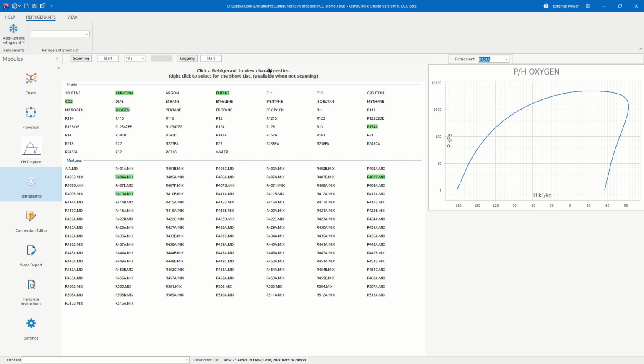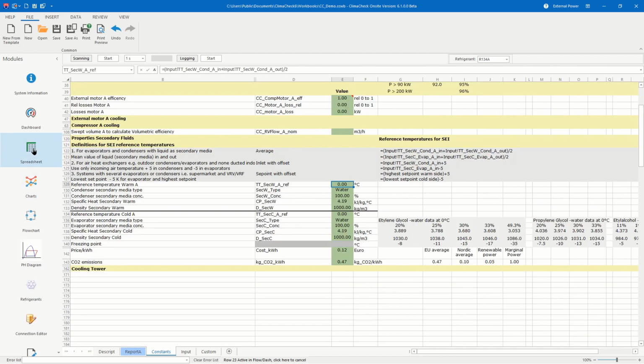And also we can change the scan interval here. And if you're using a PA Pro 3 and you are about to do a long measurement, I recommend to use 60 seconds as a scanning interval. But now when I am reading data from a file, I can use 1 second. And we can go to the spreadsheet to show.